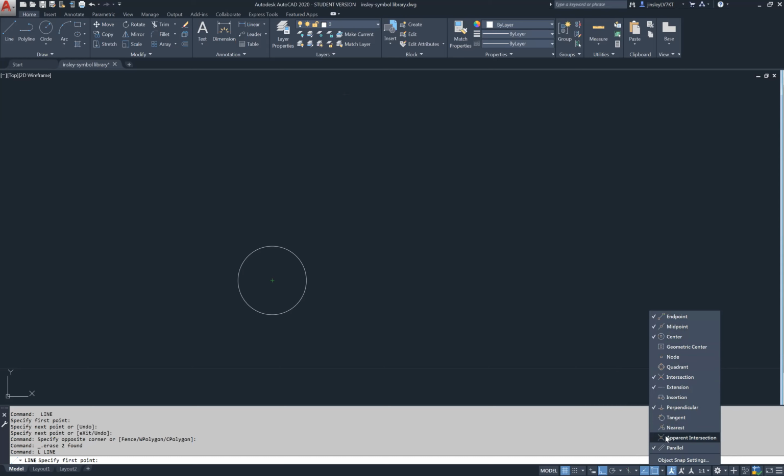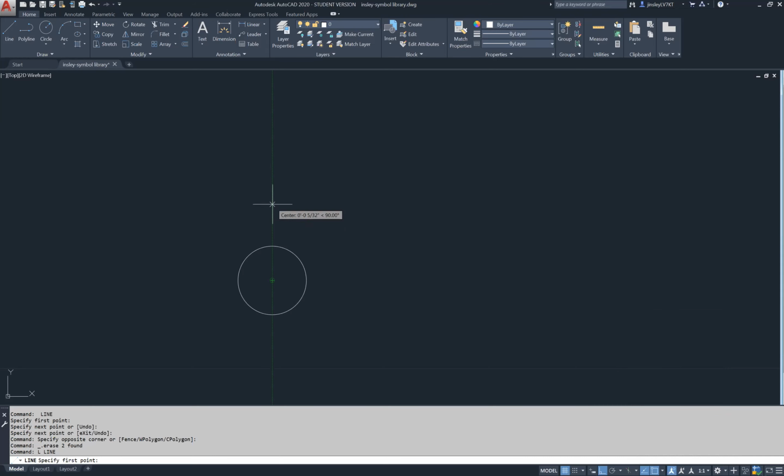And it can be really, really useful. So if I place my marker in the middle, I can track upwards a specific distance. The way I do that is I move upwards away from my green plus sign, and I type in how far I want AutoCAD to jump.